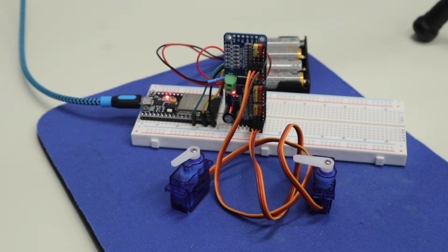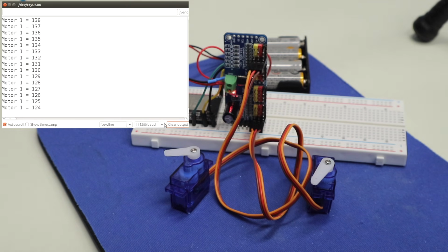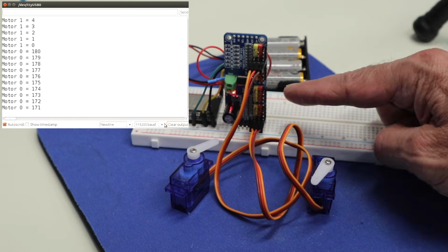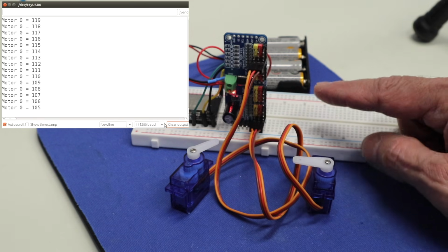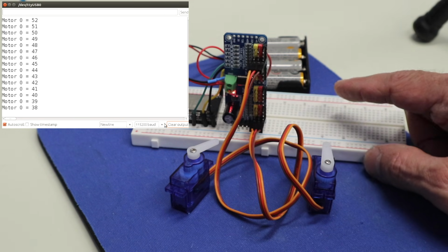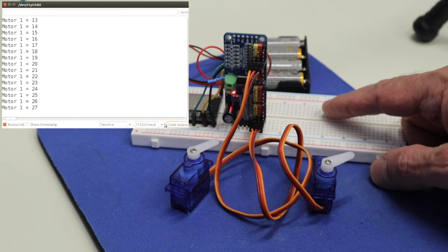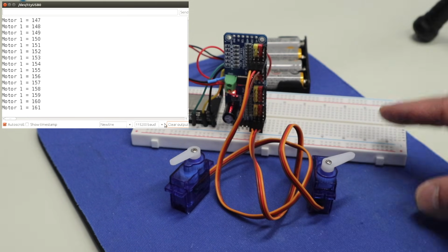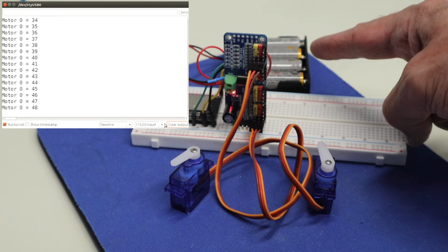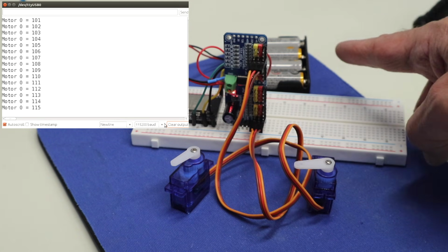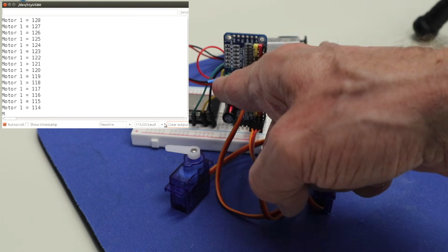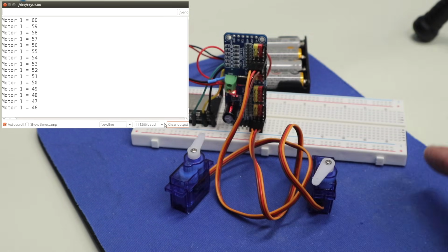And so here's our PCA9685 set up with the ESP32. As you notice, I've got it onto a breadboard. Because it had a right angle connector, I just mounted it directly to the breadboard. It's being powered from the 3.3 volts on the ESP32. The ESP32 itself is being powered by the computer. Back over here, I've just got 4 AA batteries, which is a really good way of powering servo motors, and those are connected to the power terminal on the PCA9685.